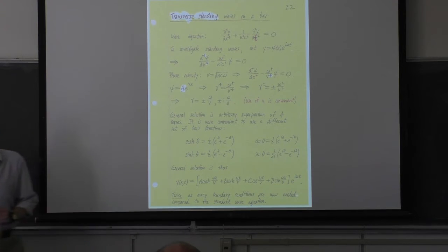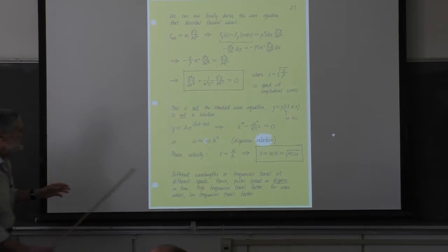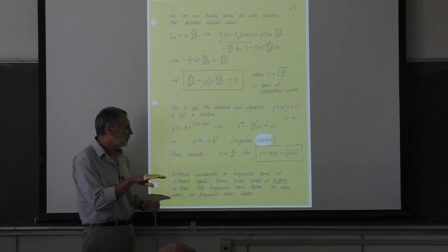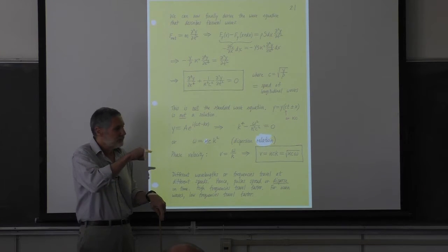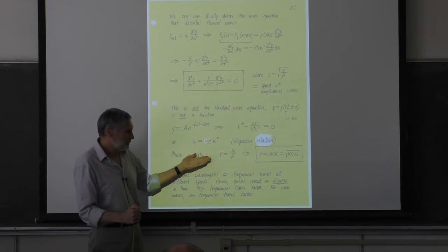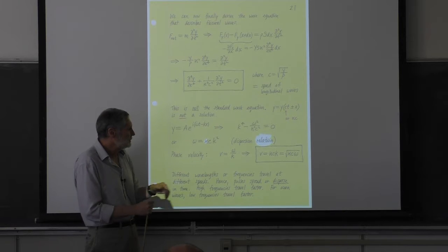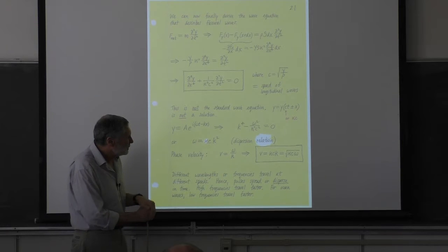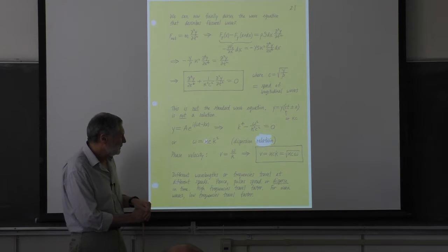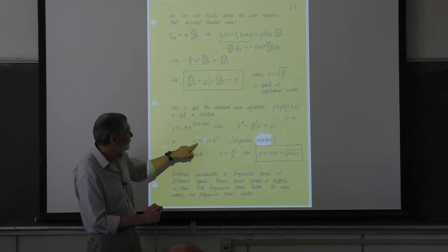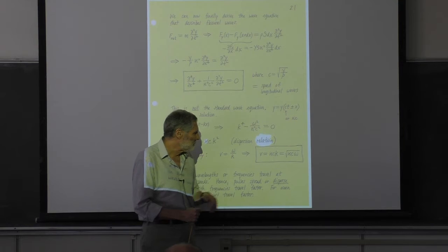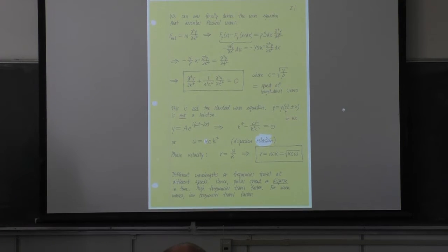Remember the phase velocity is what we did yesterday towards the end. The phase velocity is for a wave of definite wavelength or definite frequency. It's the speed of that wave. It's the distance divided by the time, and that's what this is right here, as I reminded you yesterday. So for flexural waves, the phase velocity is, from the dispersion relationship here, we get this. Either of these expressions are equivalent. So we have a wavelength-dependent phase velocity.